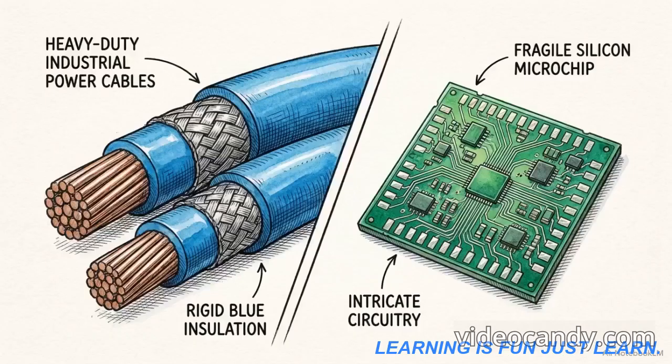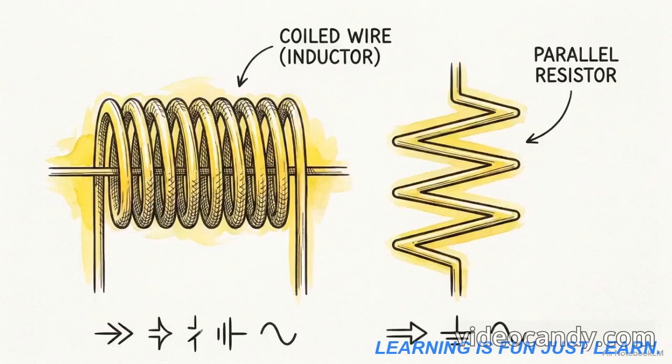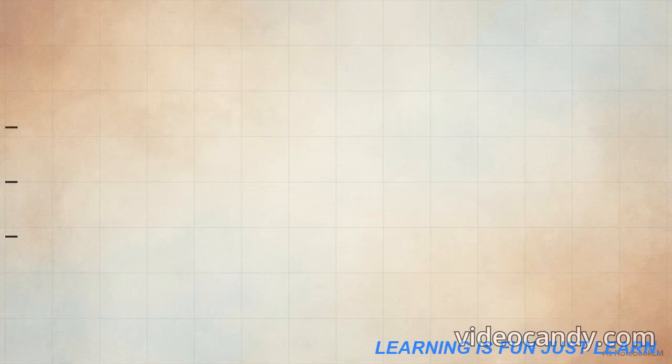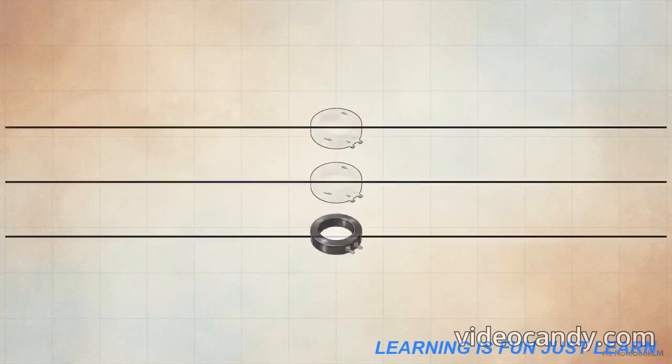When monitoring these systems, you cannot wire high-power industrial lines directly into delicate programmable logic controllers. Instead, the system relies on instrument transformers. Current transformers, or CTs, measure the amperage. Potential transformers, or PTs, step down the voltage to readable levels. We also gather supplementary environmental data. Differential transformers track physical displacement, while resistance temperature detectors monitor thermal conditions.